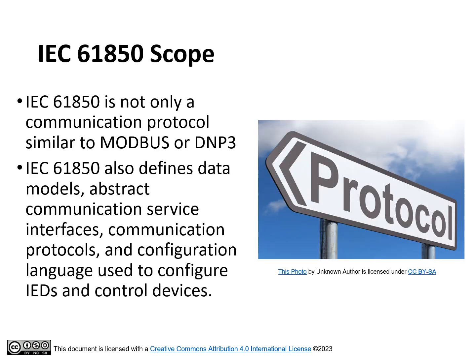As we can see from the IEC 61850 parts, IEC 61850 is not only a communication protocol similar to Modbus or DNP3. In addition to the communication protocol, IEC 61850 defines data models, abstract communication service interfaces, communication protocols, and configuration language used to configure IEDs and control devices.